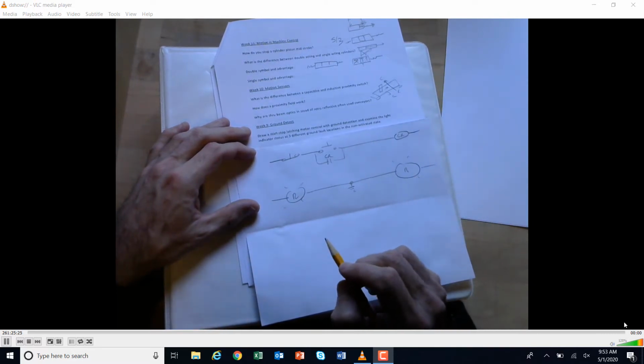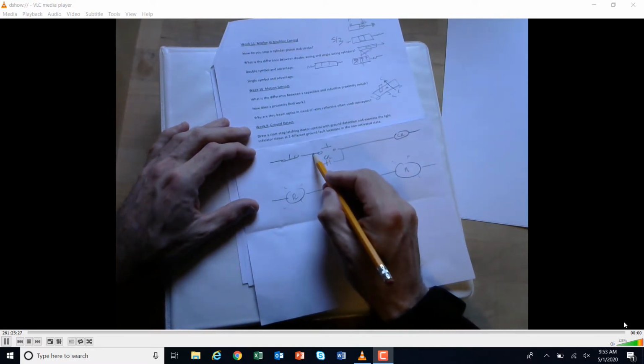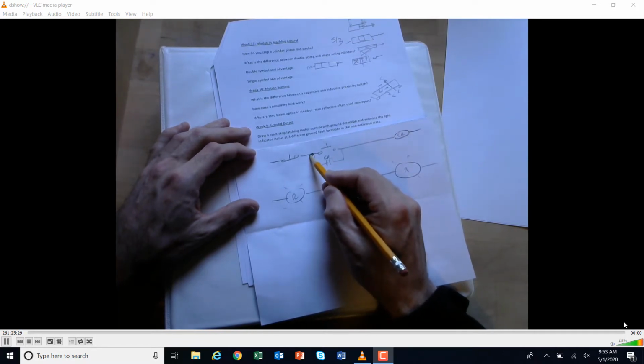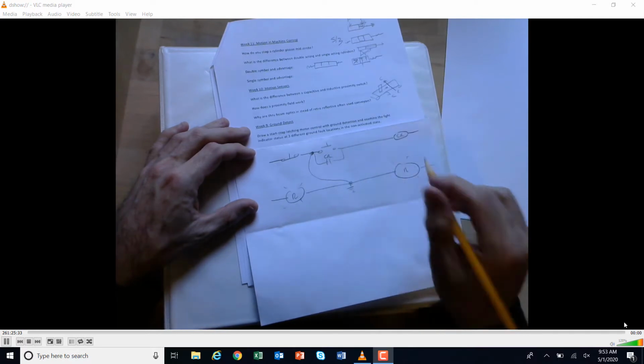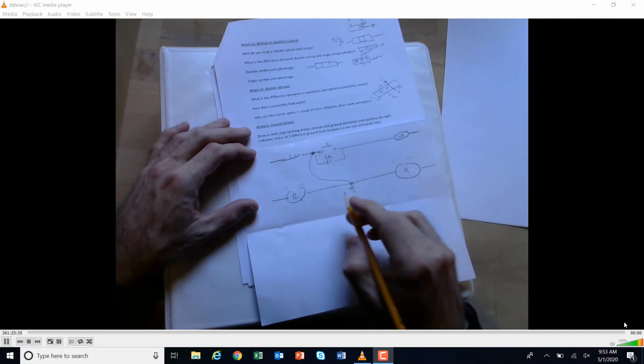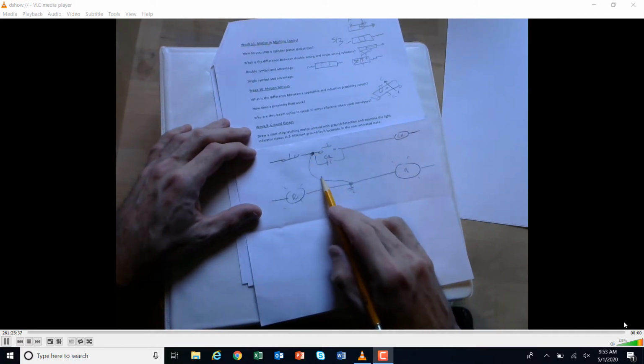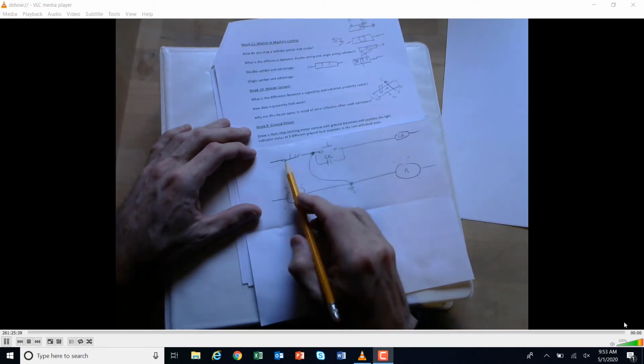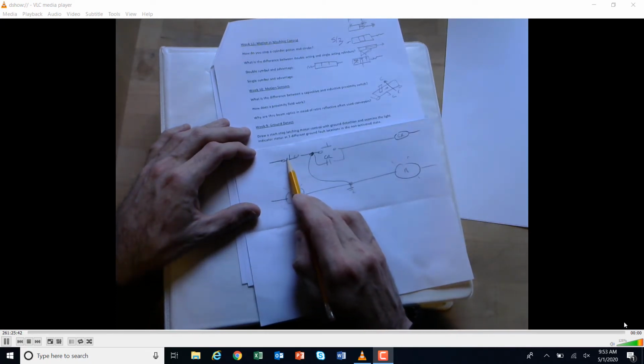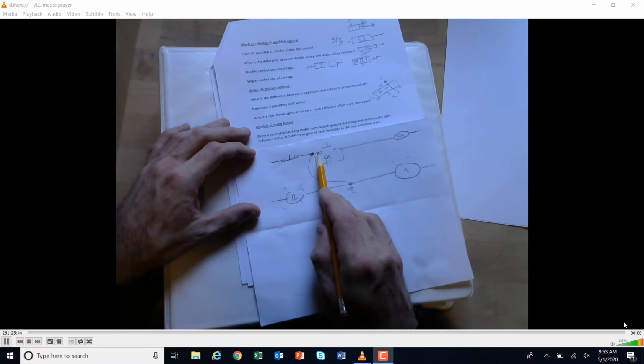These were my lights. Okay, let's say they're red lights. So that's where we talked about, well, what happens if you get a ground detect at this location here, right? And then, whether buttons are pushed or not or whatever. In this particular case, we had ground detect here, and we hadn't pushed anything. Well, there's flow through this button because it's closed. There's no flow through that because it's open.